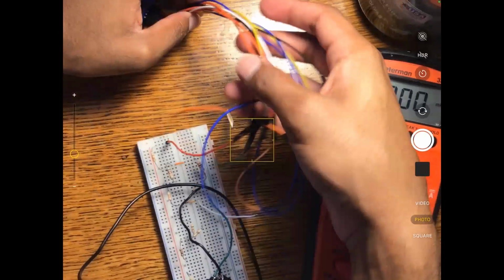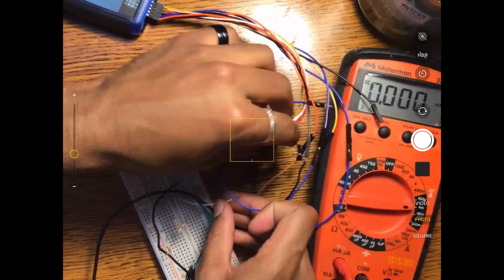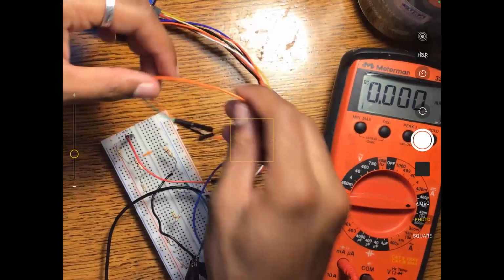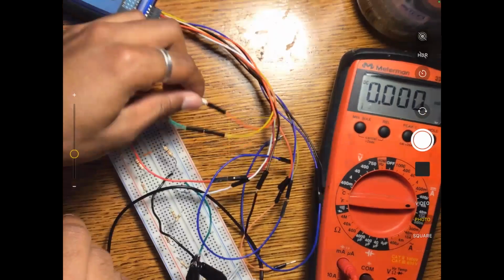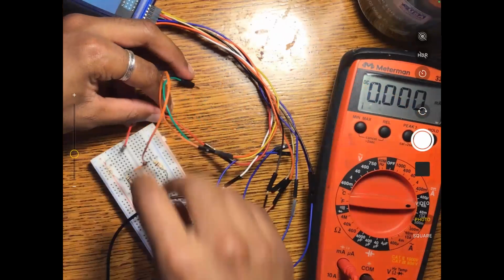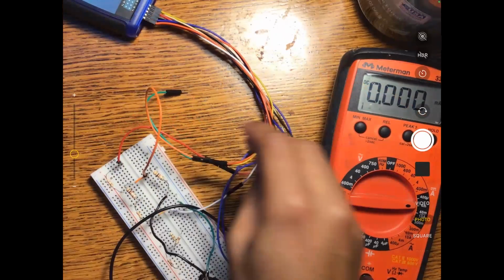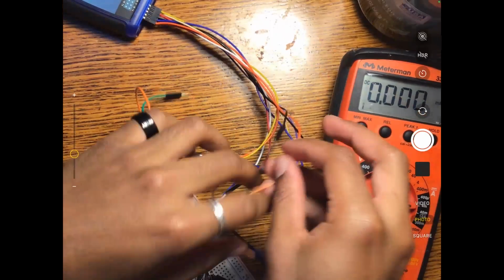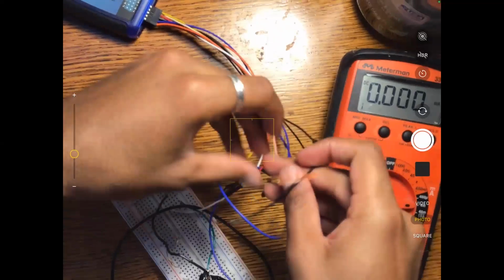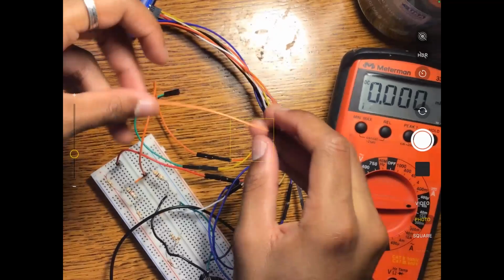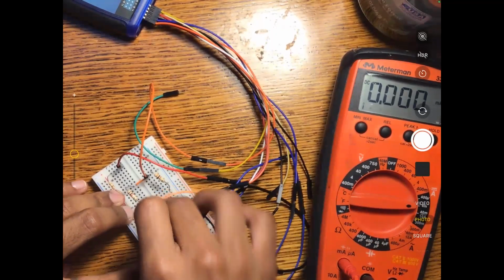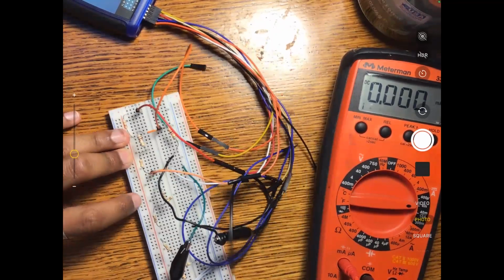Now I just want to measure the voltage, right? Or at node 2, which will be the voltage drop of R3. So what I'm going to do is get my positive channel 1 cable and connect that at the orange right there, and then connect my channel 1's negative at my ground. So I'll just find that right there. Okay, cool. So that is my circuit.